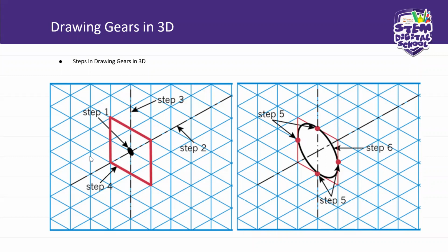You start by making this square. This should be a square, although it is skewed in isometric drawings. So you just follow the line of the squares and you make that. You are planning your drawing. And then you make construction lines this way, and you have this other construction line. That's supposed to be your construction lines for the circle.